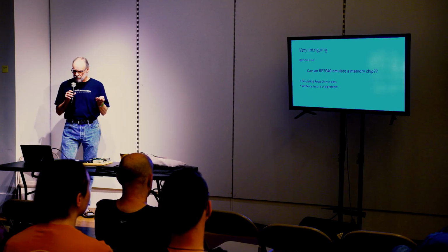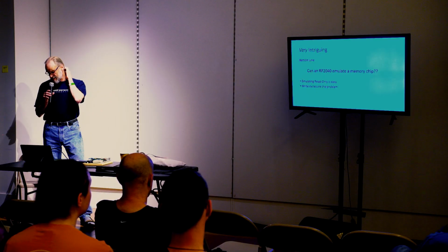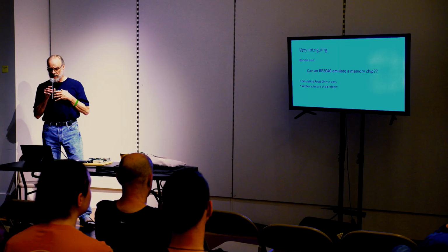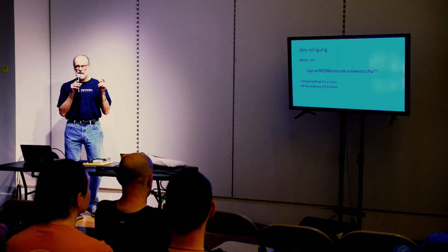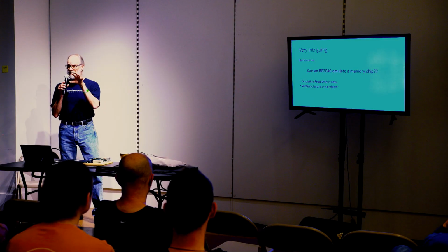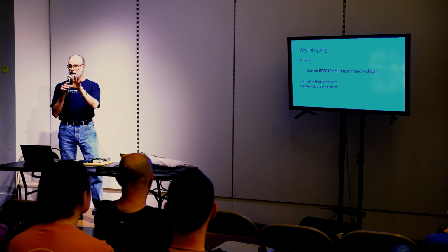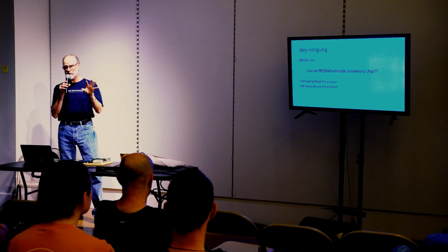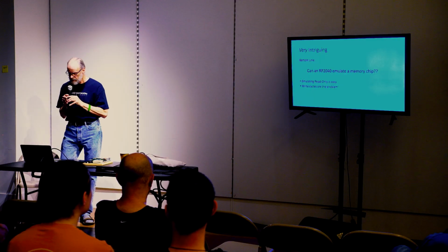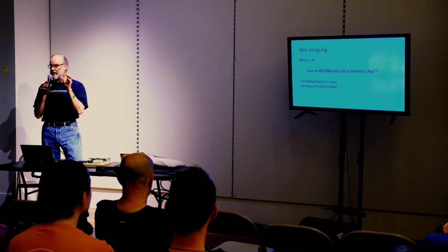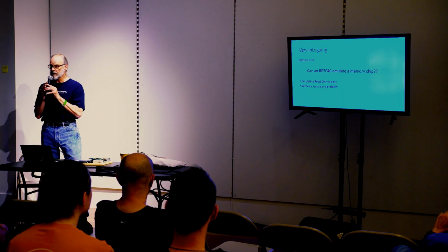So that was super intriguing, but the bottom line was, could an RP2040 actually emulate a memory chip? And I will point out that if you just want to emulate an EPROM, just read only, that's easy. I'm pretty sure anyone in this room could do it in one screen full of code. It's just not hard. Write cycles are the problem, catching the data off the bus at the right time.